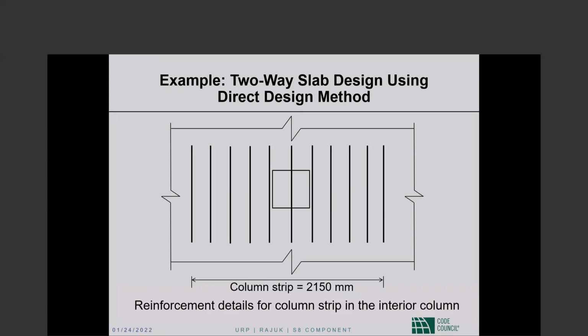Okay. So is it possible to design flat plate or slab on steel columns? Are there any design considerations specific to that? There is so-called lift slab construction, and that requires shear heads.